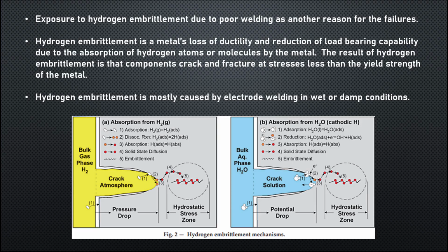The figures below show how the process of hydrogen embrittlement occurs. At room temperature, hydrogen atoms can be absorbed by carbon steel alloys. The absorbed hydrogen may be present in either atomic or molecular form. Given enough time, the hydrogen diffuses to the metal grain boundaries and forms bubbles there. These bubbles exert pressure on the metal grains. The pressure can then increase to levels where the metal has reduced ductility and strength.